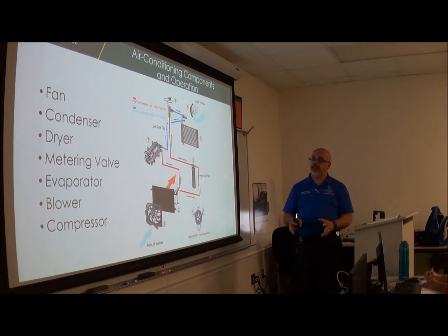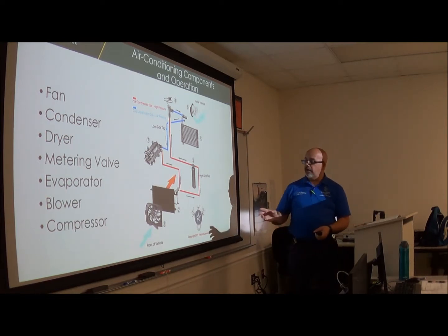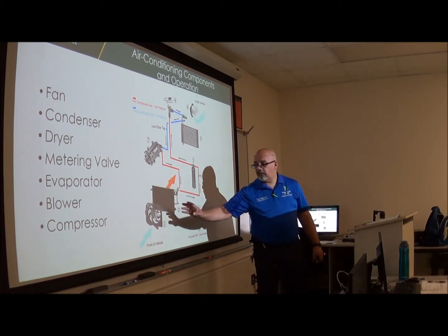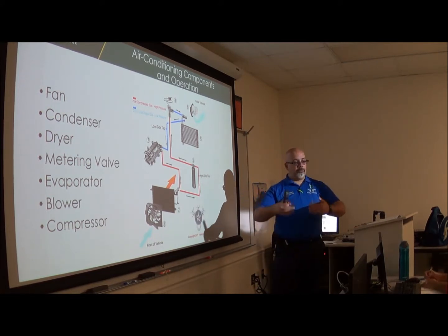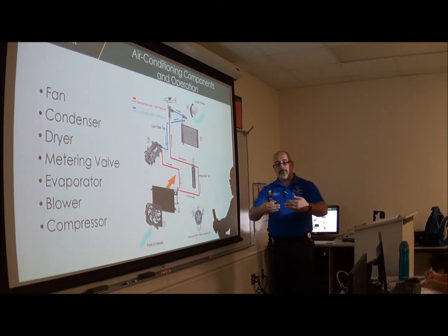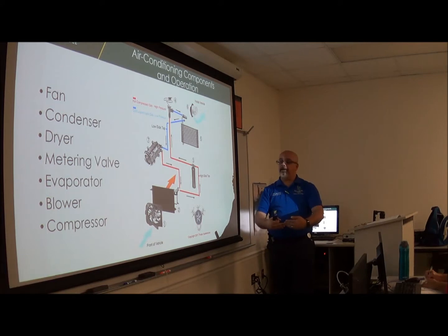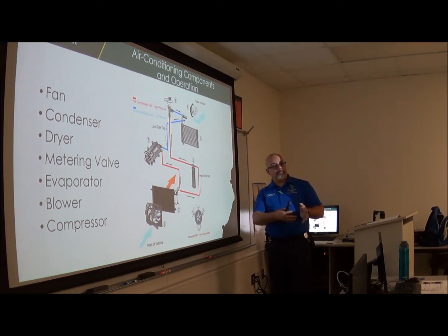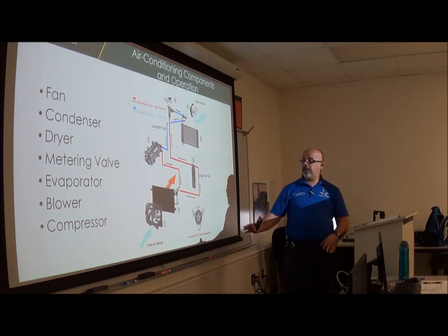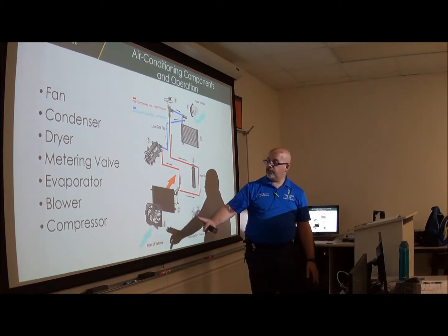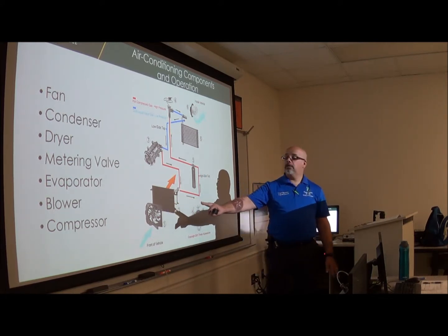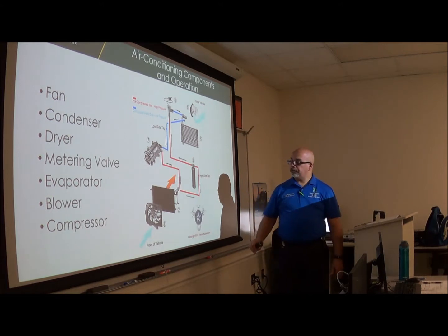In this case, we have number 1, which is the fan. Depending on whether it's in the front of the vehicle or behind the radiator and the condenser, it will either pull or push the air depending on where the position is. In this case, we're showing it in front, so it's pushing the air through that condenser.